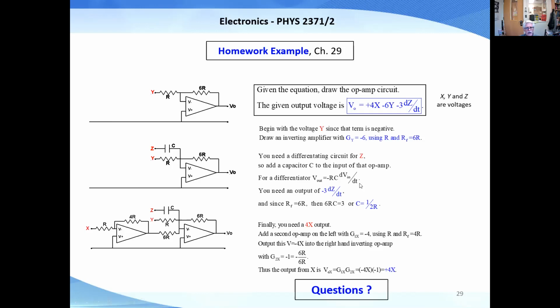In general, for op amps, especially like the 741, you don't want to have too small resistors or too high of resistors. Like, you don't want to have R is 1 ohm, 6R is 6 ohms. You don't want to fry anything. Or even megohms, 1 megohm, 6 megohms. Pick something reasonable. Good question.